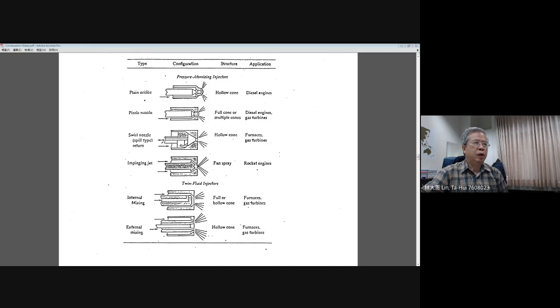And those swirl nozzles, basically they tell you the liquid fuel will be influenced by the pressure itself and also by the swirl motion of the fuel spray. This typical spray nozzle is widely used for gas turbines. For example, the simplest nozzle, and we will explain it later, and I will even give you some flow structure measurements to let you know the drop size distribution and velocity distribution for a given spray.